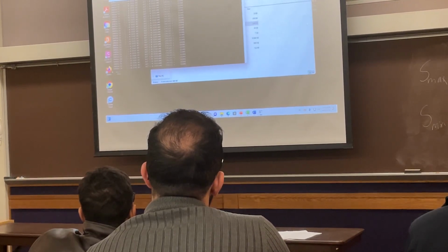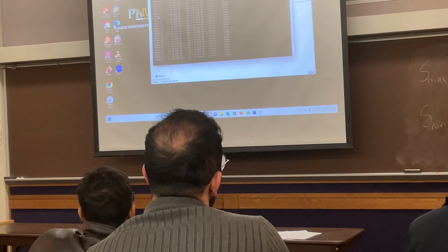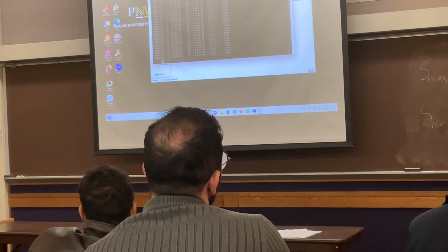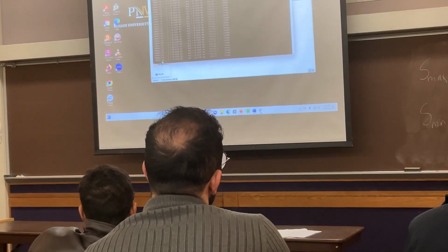right now it's running, A is done, and the second part, B, is running. Whenever it reaches failure, it automatically goes to the next level. So it's C, the first two are already done. As the stress level was higher, there are shorter numbers of cycles to fail. So it solves it cycle by cycle.